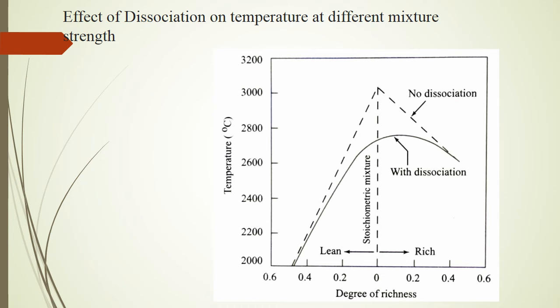The presence of carbon monoxide and oxygen in the gases tends to prevent dissociation. This is noticeable in the rich fuel mixture, which by producing more carbon monoxide suppresses the dissociation of CO2. On the other hand, there is no dissociation in the burnt gases of a weak fuel mixture as the temperature produced is too low for this phenomenon to occur.